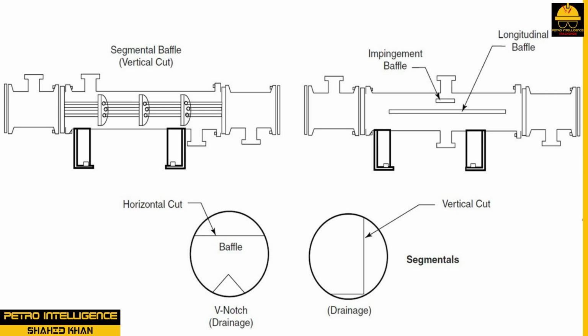Single-pass exchangers do not need a baffle in the inlet or return head. Multi-pass exchangers requiring 2 passes will have a single baffle in the inlet channel head. A variety of baffle arrangements are available. Cost goes up with each pass. Additional passes are often needed to provide adequate fluid velocities to prevent fouling, internal buildup of material, and to control heat transfer.